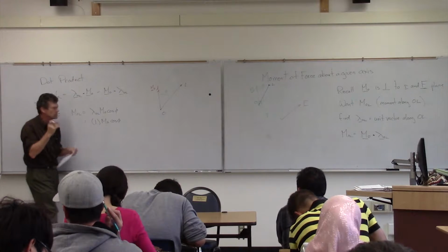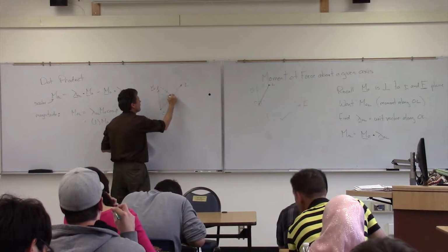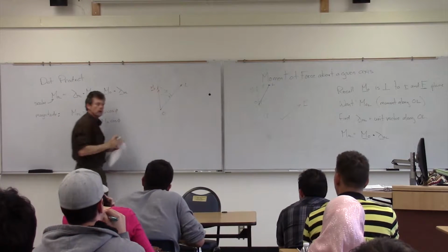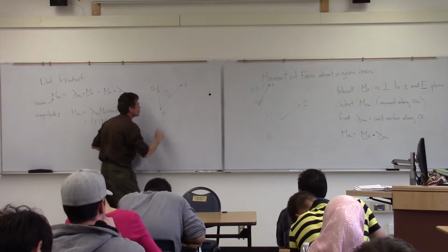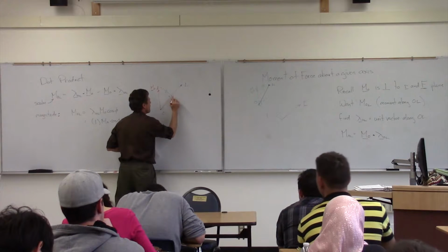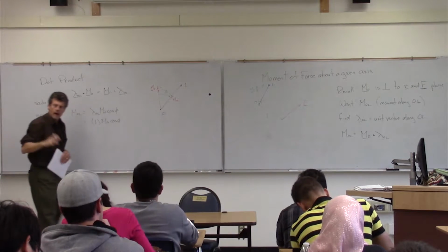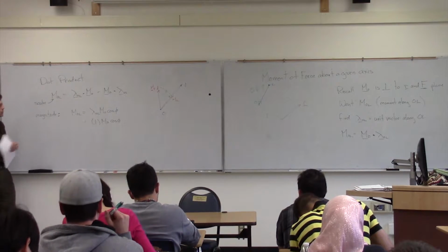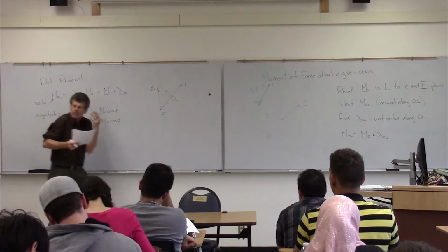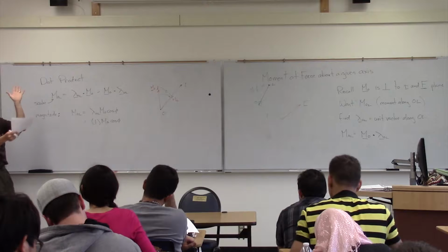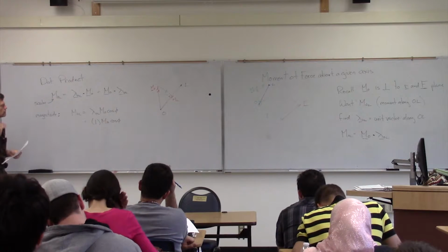And the nice thing is then when we do the cosine of that angle, basically, what we're getting now is a projection of that moment now on there. So it's just simply projecting the magnitude of that moment now onto that line there. So it'll be a little less than if it's some angle. If it's 1, it'll be the same. Anything else, it'll be slightly less.